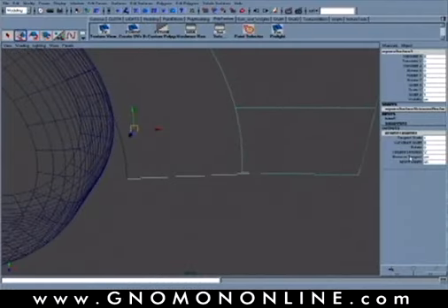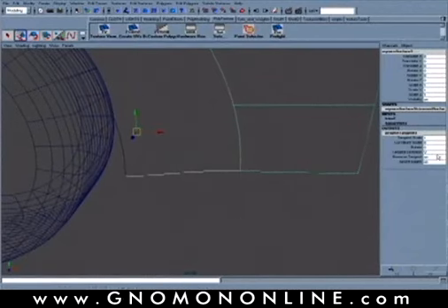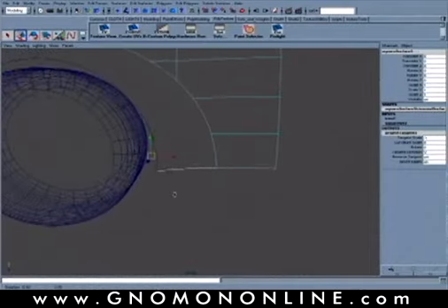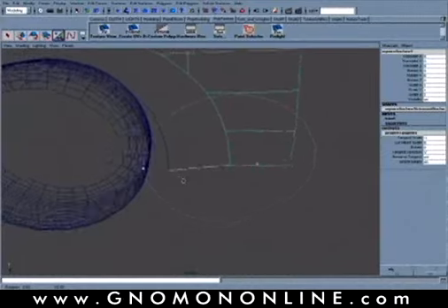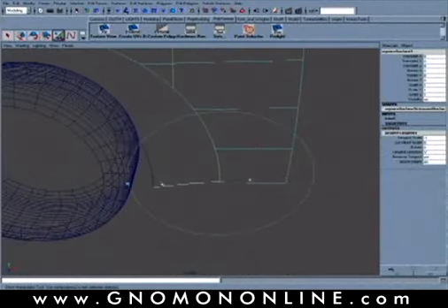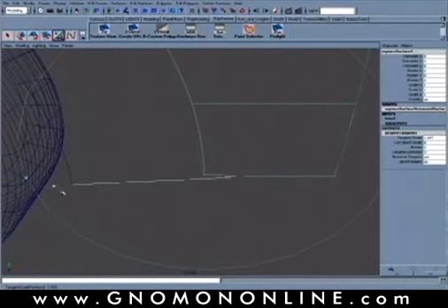There's the option of reversing tangent, which you could turn on, which will flip it the other way. Or if reverse tangent was off, you could go in and take your tangent scale value and make that a -1 instead of a +1. That will basically do the same thing. If you're doing this and you hit the T or show manipulator, you can also run the tangency through some manipulator control. So hitting T show manipulator will give you things like a control to scale that tangency. And again, we can see the positive or negative feedback or kind of reversing that over the surface.